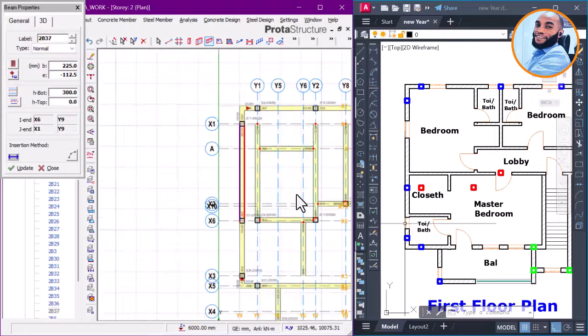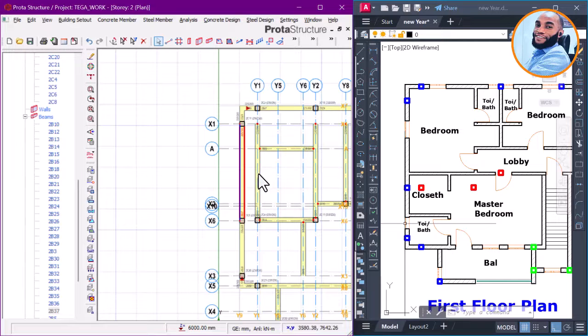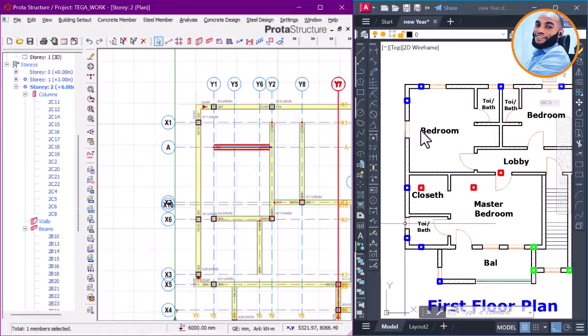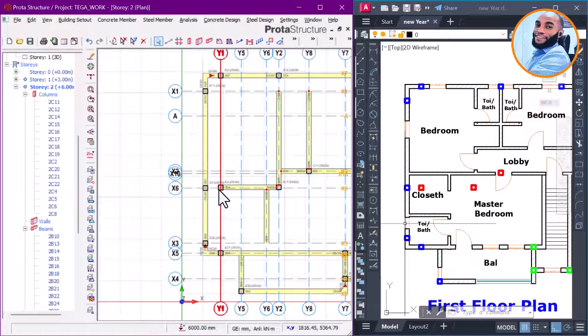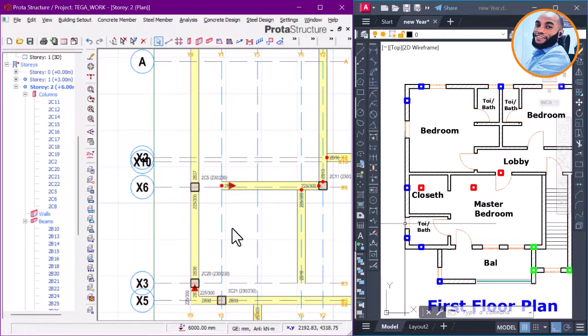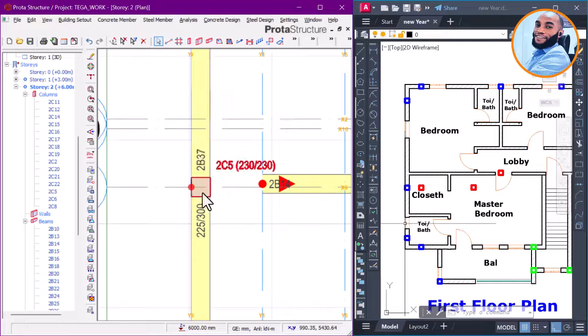So right now we will remove this beam here, this other one here, because there's no beam from here flowing again, so take it off. That's fine. In that case also we'll take this one off, because there's no beam around here. Can you see that? Take it off too. Okay, that's fine. So we now come and take off this column. Okay, this column will also go off. Now since we have provided a column here, make sure once you provide a column, go and provide a support under it, on the story below. So go to Story 1 and provide a cantilever beam at this point.